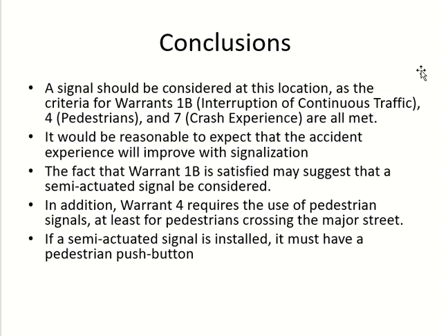Now warrant 1A, the 8-hour volume. I'm talking about the 8-hour volume. If you meet warrant 1A, that means both directions according to their capacity have high volume. Both minor road and major road, according to their capacity, they have high volume.